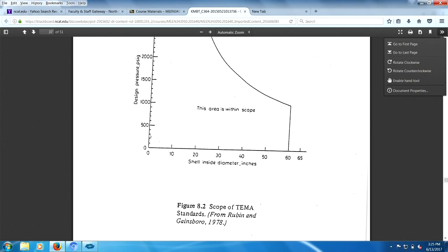There are two other major heat exchangers we're going to talk about. One is a plate heat exchanger, and the other one is a spiral heat exchanger. Their upper limit is 300 PSI, right? So right across here, you can see those two other heat exchangers can work absolutely wonderfully. But you can see what the shell and tube can do for you, just to give you an idea. And I already said you can go up to 10,000 PSI easily.